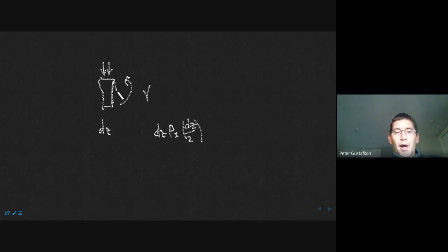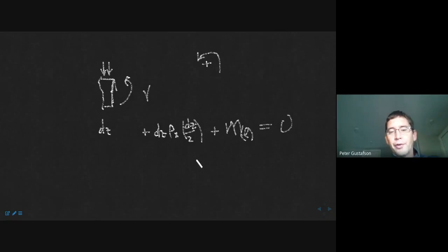Now, if we're doing moments counterclockwise positive, so that would be about the end point, that would be a positive number plus the moment at L is equal to 0. And by the same arguments, and in fact faster this time, because we get a dz squared over 2, the limit of that equation as dz goes to 0 as we approach the edge means that M at L is equal to 0.